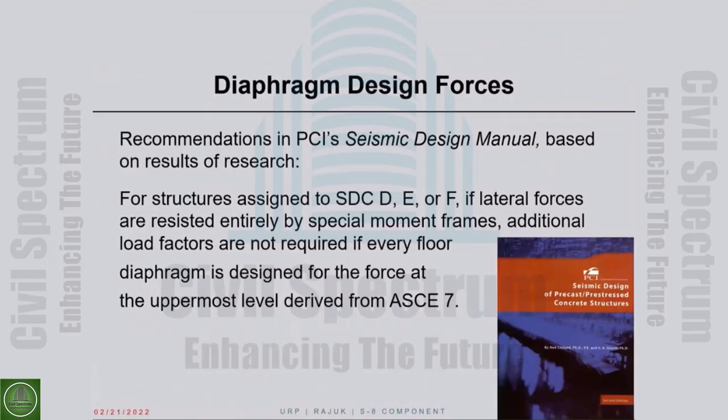So based on these observations from many sources, in PCI's Seismic Design Manual that Ned Cleland and I put together many years ago, we made some recommendations for structures assigned to design category D, E, or F. If lateral forces are resisted entirely by special moment frames, additional load factors are not required if every floor diaphragm is designed for the force at the uppermost level.